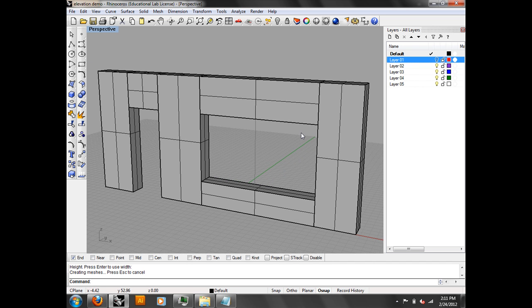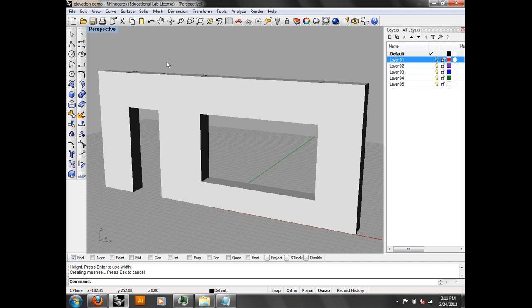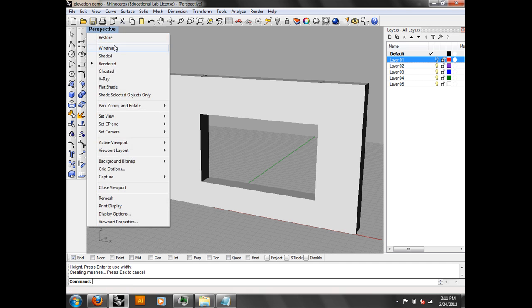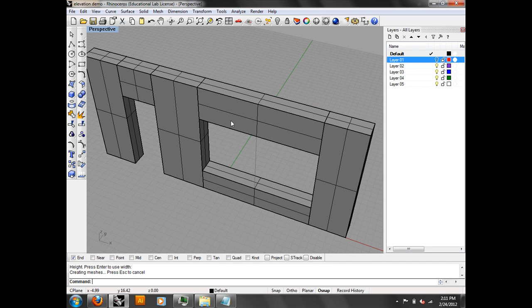Okay, what's wrong with that? It's pretty good. Midpoint seams that you're going to snap to. You've got seams in it. If that's really meant to read as a solid wall, you go into Make 2D and you've got all those seams running down that piece. You get the geometry, and if you rendered it, it looks pretty good, but the geometry's not quite right. Now you might do this if the depth is changing slightly, or these are pulling out, pulling in, and you want those to read differently. But if they're meant to read as one thing, they should read as one thing.